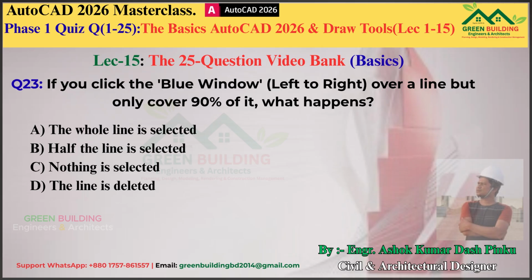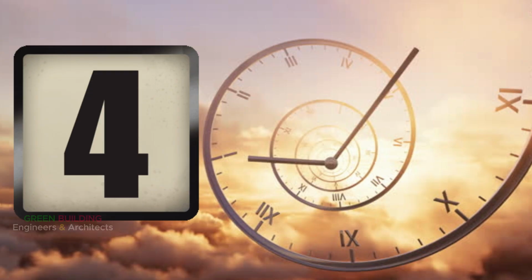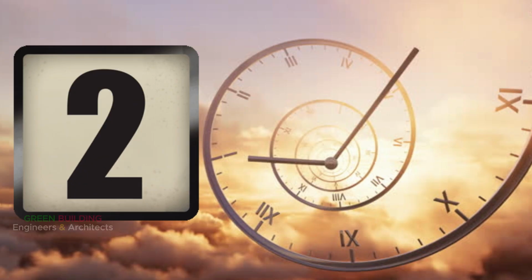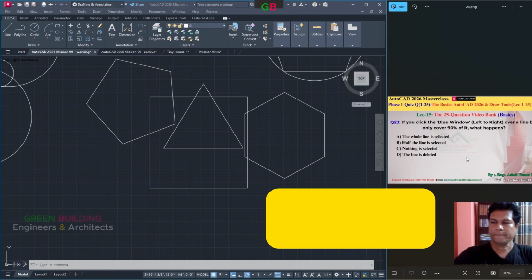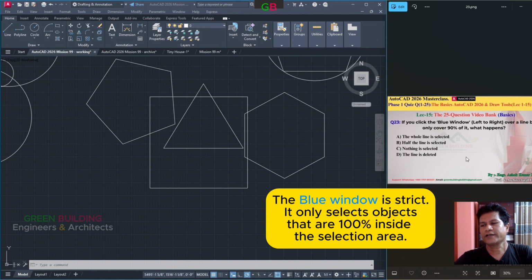Question number 23. If you click the blue window left to right over a line but only cover 90% of it, what happens? Option A, the whole line is selected. Option B, half the line is selected. Option C, nothing is selected. Option D, the line is deleted. The correct answer is C, nothing is selected. The blue window is strict. It only selects objects that are 100% inside the selection area.